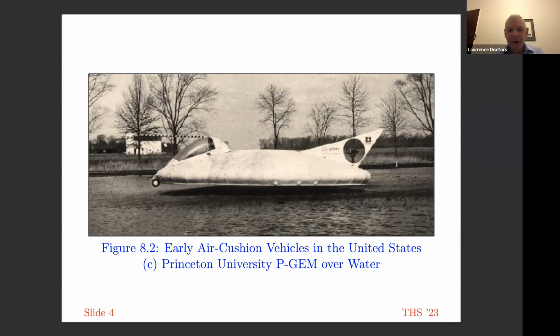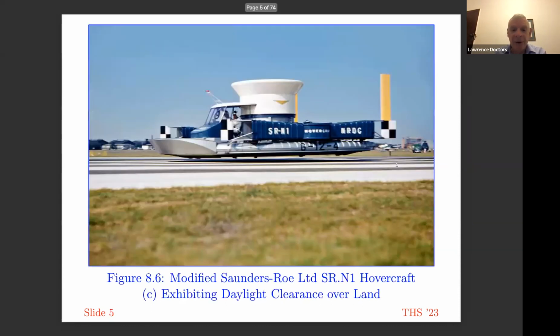So the hovercraft has to generate an additional force to overcome the wave resistance, but there's also this additional momentum drag, which I can send the formula for if anyone is interested. So the skirt actually provides 3 advantages: increased obstacle clearance, reduced spray, and considerably reduced drag, almost eliminating the momentum drag associated with generating the air cushion.